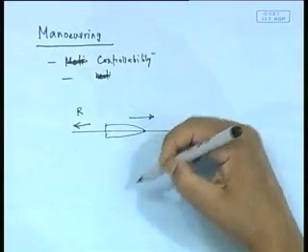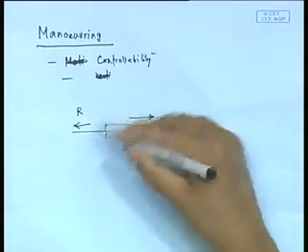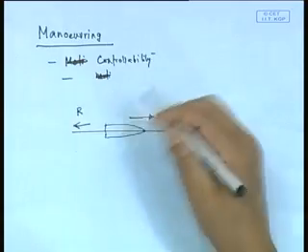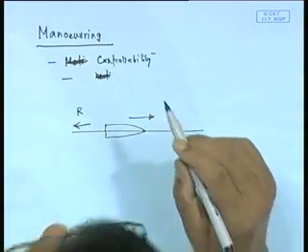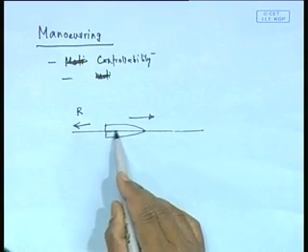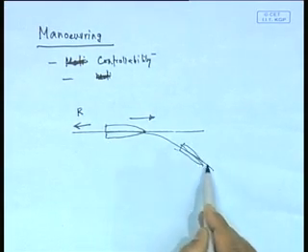Ship is symmetric geometrically, port and starboard. In fact, almost all vehicular systems are geometrically made symmetric, simply because you do not want a yaw or pitch motion coming. If there is a small one, you correct it. Now, in maneuvering, our interest is actually when the ship tries to turn or make various kinds of motion in this plane.